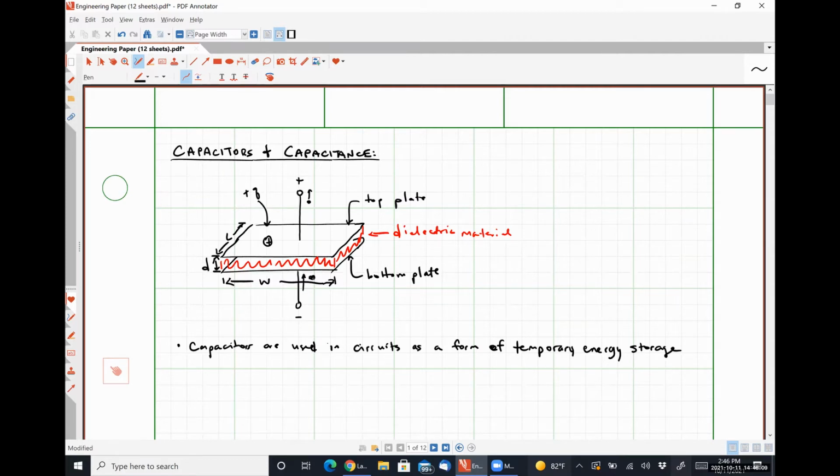So moving the charge onto and off of the plates causes what's called a displacement current. That displacement current means absolutely nothing to you guys. It's just a different mechanism for current to flow. It behaves in the exact same way as the conventional current that we've been discussing. And because this is a low-level circuits class, we're going to treat it in the exact same way, okay? So charge doesn't pass through the dielectric material. Charge just moves on and off the plates. And that's where our current voltage relationships are going to come from. All right.